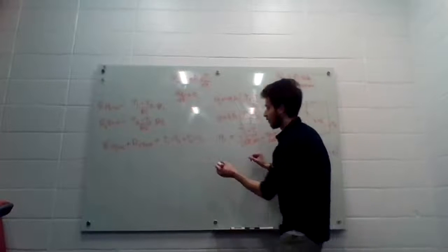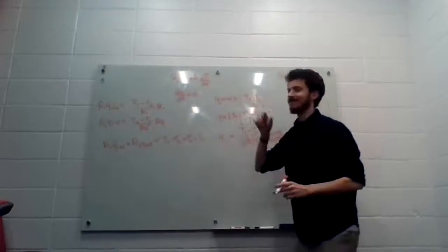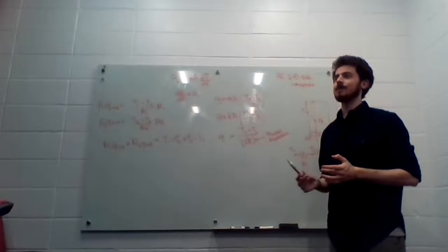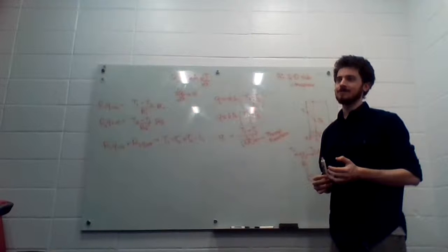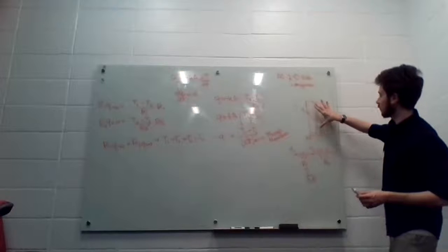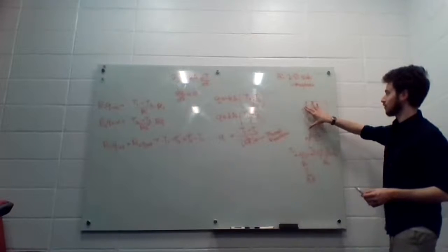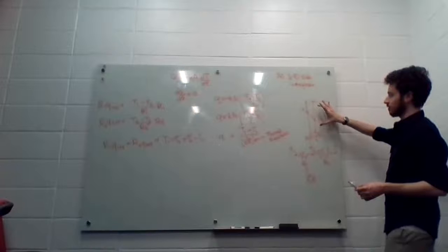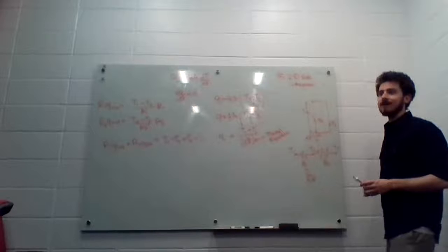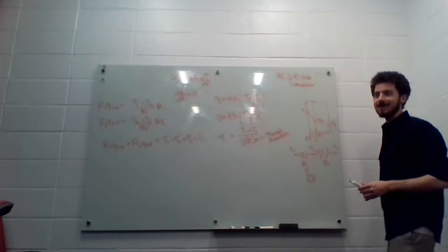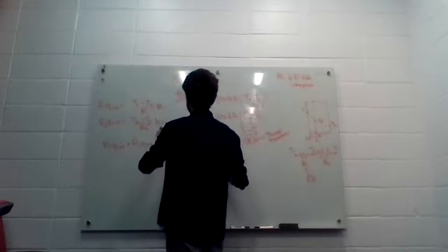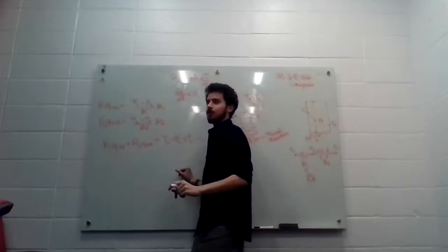Get rid of the T2s. What can I do on the left-hand side? What do we know about those two Q terms? What they're equal to? That they're equal to each other, yeah. Because if a certain rate of heat transfer goes through this first slab, there's nowhere for it to go but through the next slab, because we've got an infinite wall that also sometimes has a finite area. So we're going to replace both of these with just the term Q.